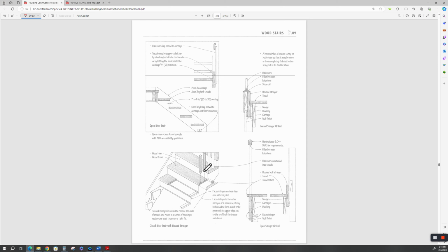Here's a wood handrail or baluster, and it's dovetailed in, and then the end caps are put on, or the tread return. I'm not a big fan of these because over the life cycle, these things break off, then you got to tear your tread apart and then haul that piece of wood out, and then try to go find another one of these that's dovetailed.